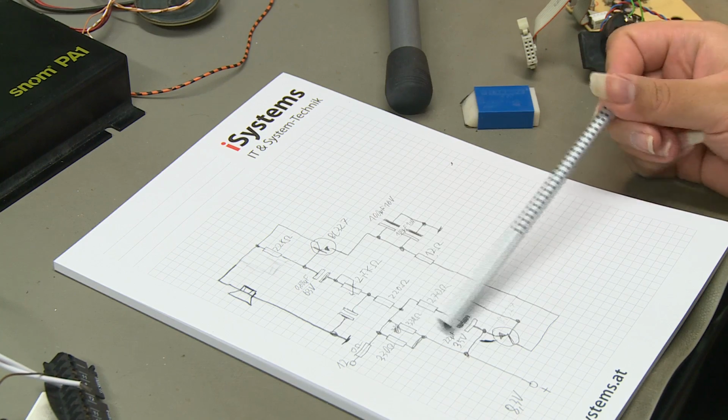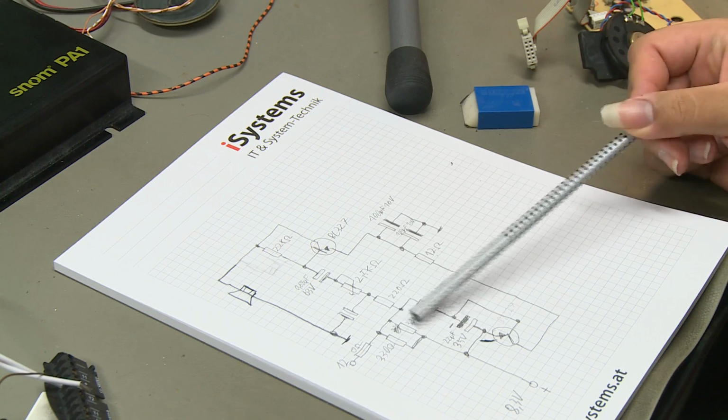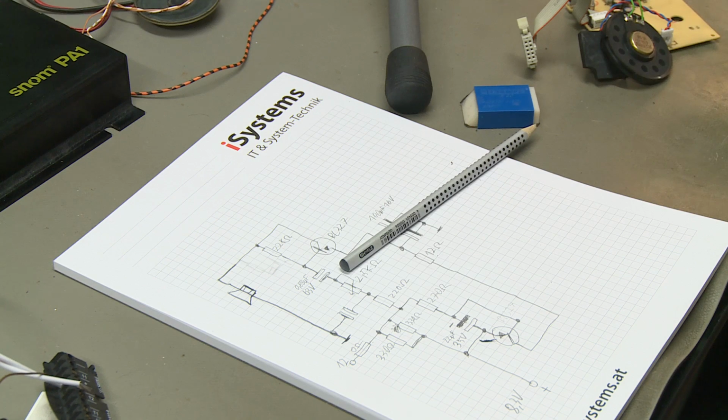It would make sense for these two big resistors over here, so that on the other side basically there's just a current sink which is driven by an audio signal, and it varies the amount of current it draws, and this in turn is then turned into the audio waveform.